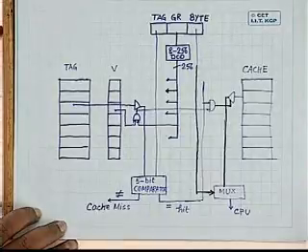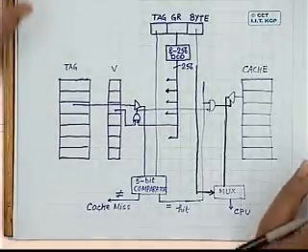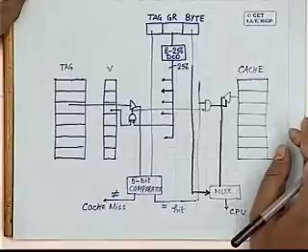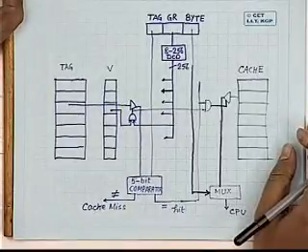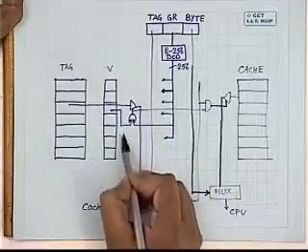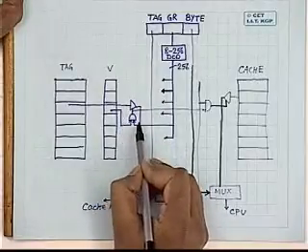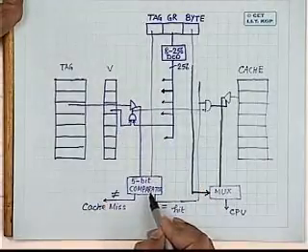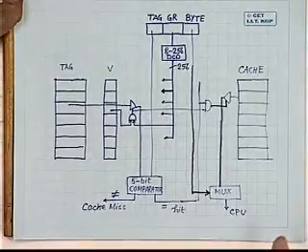Okay. So will there be any serious loss in terms of time if we do it serially, with only one comparator for two-way set associative? Yeah, if you do it with only one comparator, in that case, there has to be a sequential circuit here. So the job which I can do in only one clock period has to be expanded to 2 clock periods. Just a matter of nanoseconds.